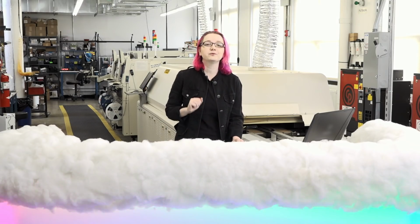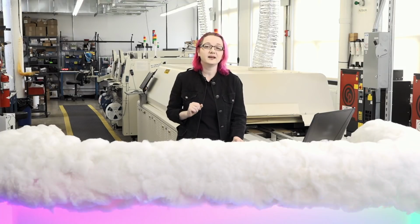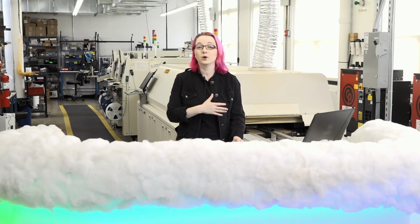The first and most obvious metadata is the time the data was entered into Adafruit IO. And this is handled for you when you post data to the feed. We timestamp it. The second metadata is location, where you can set where on Earth the data came from. That metadata is something you have to add yourself.